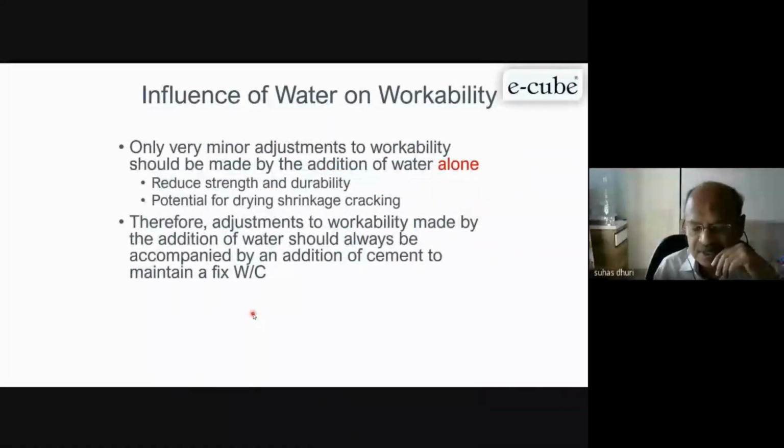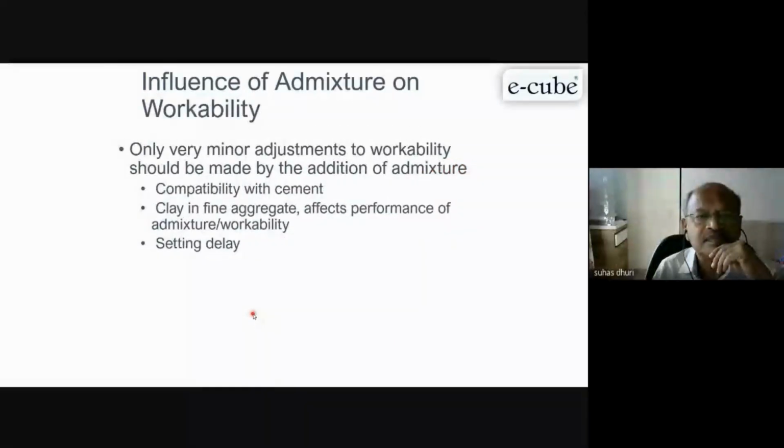I think we have discussed this. Compatibility with the cement is also a major issue for getting proper bleeding. And sometimes there is clay in the fine aggregate that affects the performance of your admixture and causes setting delay. It's possible because of clay content in your fine aggregate.